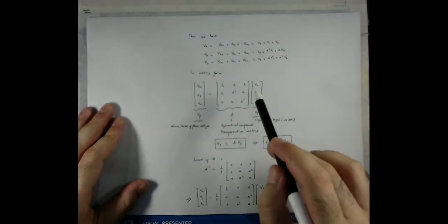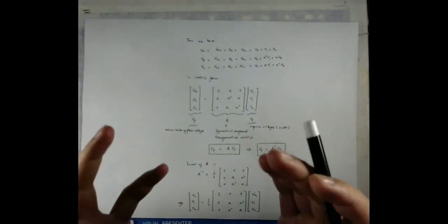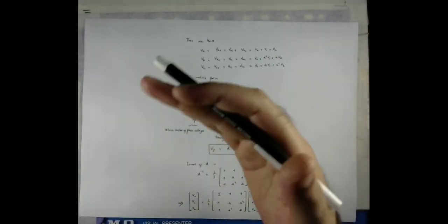And as I mentioned, for a zero sequence the magnitudes are equal and they are in phase. For the positive sequence, once again, the magnitude of the positive sequence voltage, or current, is the same, only the other quantities are phase shifted by 120 degrees. And similar is the case of the phase C quantities.